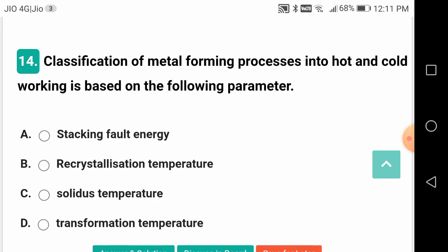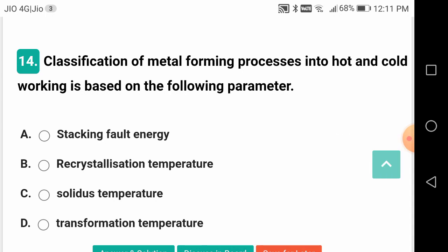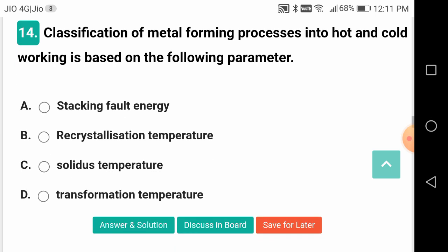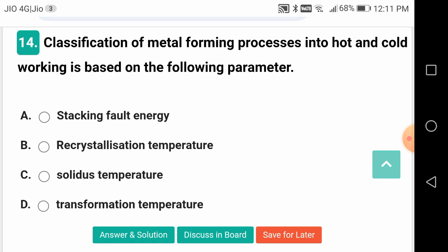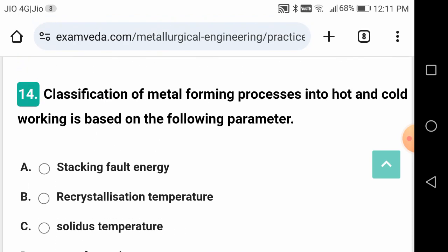So what we are doing actually? You are applying a force, okay, because of which the metal billet is going to take the shape of the opening, and in the process it is subjected to compression, but it is indirect compression, right? Because your die is going to oppose the motion due to the force you apply.